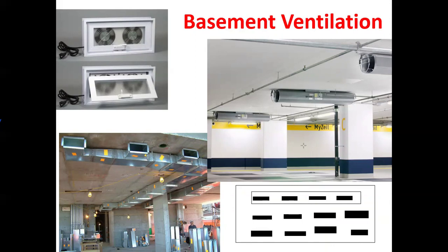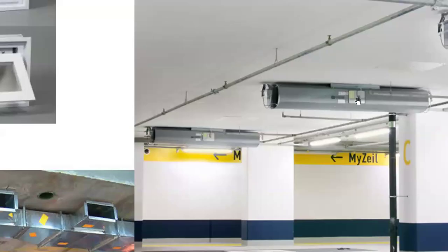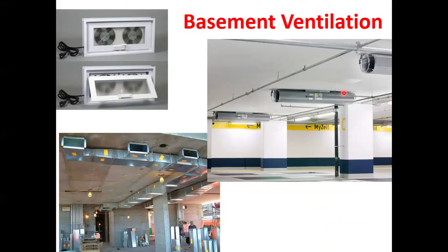That's why here you can see something attached right here. This is the IQ board, which means the PLC board for the entire set of fans. And for these feedbacks, the CO sensor is not placed on the fan. Instead, it is placed on the beams, that means the columns. Okay, that's it. So especially for high-end commercial buildings, if the client is wealthy, they will go with this kind of jet fan assembly.